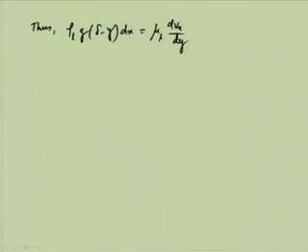Now, if we do the force balance, what we get is rho L g into delta minus y into dx equal to mu L into dvx by dy into dx, plus rho v g into delta minus y into dx. We write dvx by dy because velocity varies along the y direction only, we assume. Here v is the suffix for the vapor and L is the suffix for the liquid.